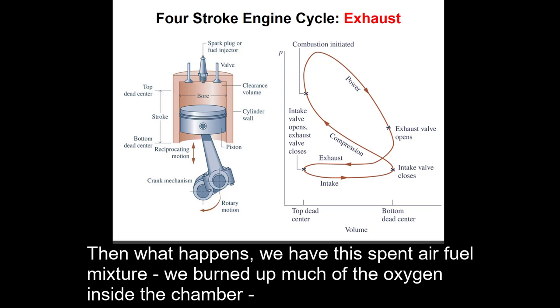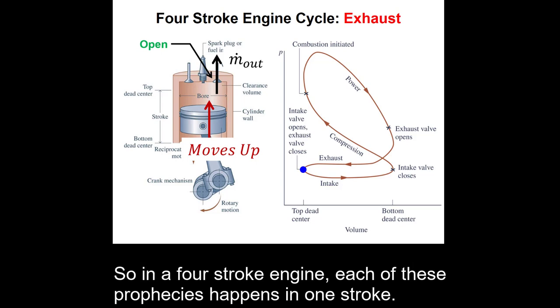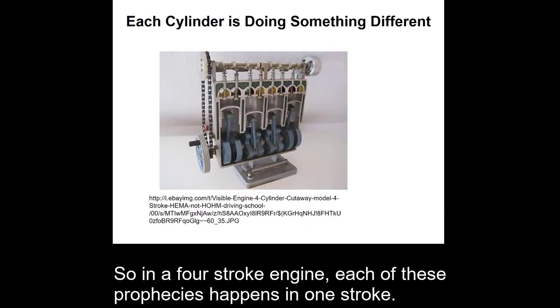We've burned up much of the oxygen inside the chamber, so we open the exhaust valve, the piston moves up and forces the majority of the air out of the cylinder in this exhaust stroke. So in a 4-stroke engine, each of these processes happens in one stroke.